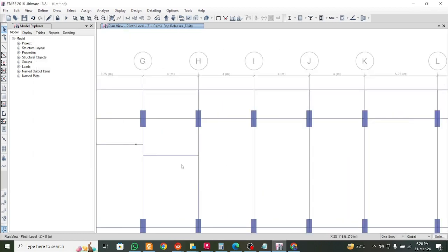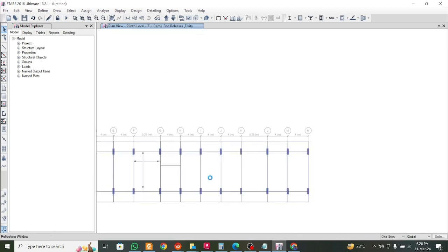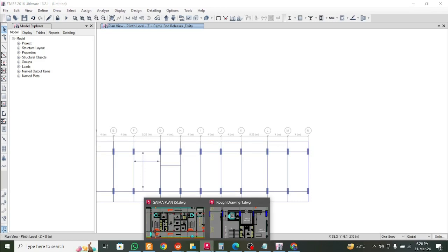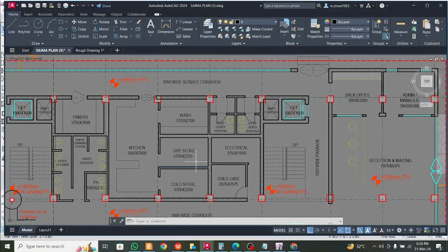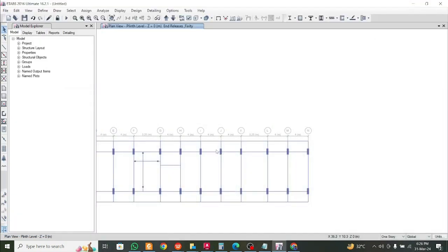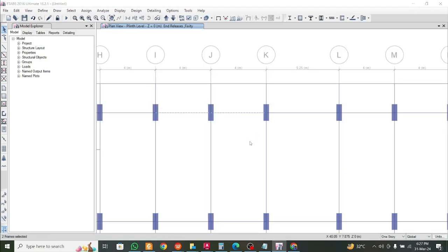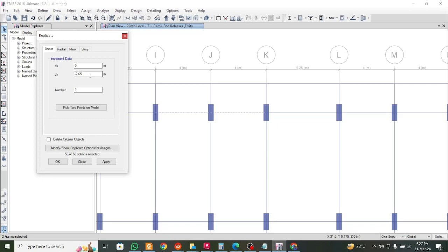We'll release the moment later. Okay. So this is done. And now leave one span, and then for the next two spans we can do the 2.65 offset. Select these two, Ctrl plus R, replicate 2.65, and hover over to apply. So we're good, and okay.